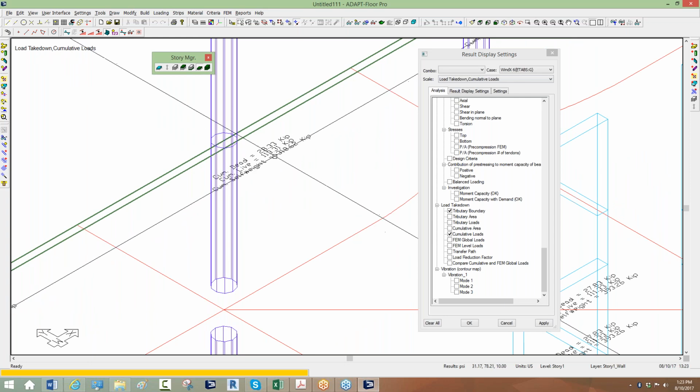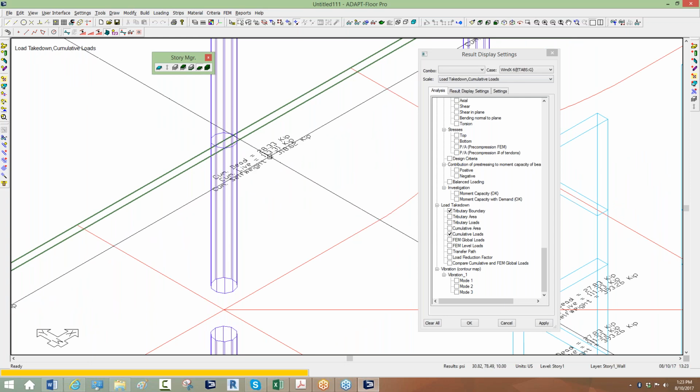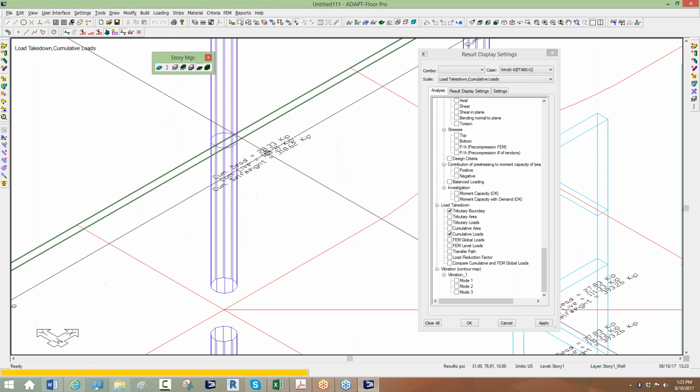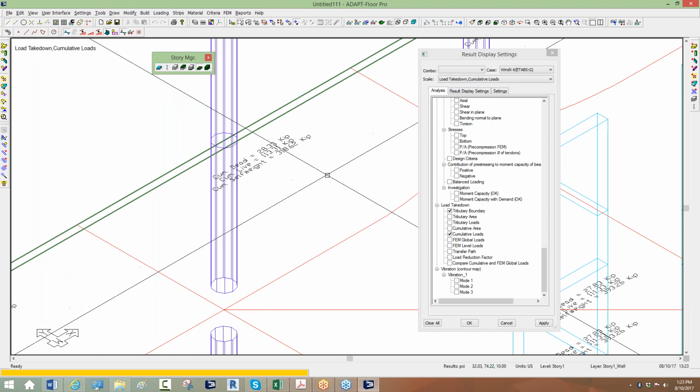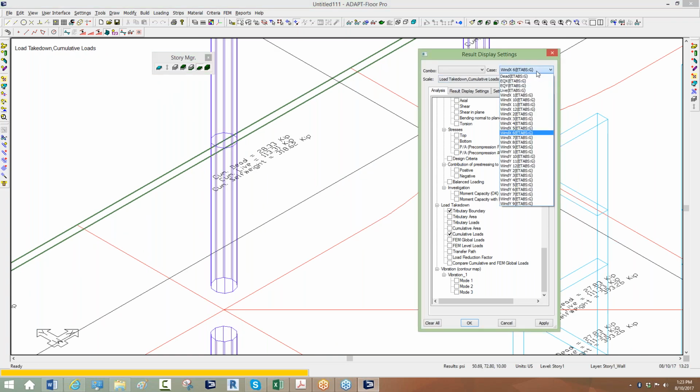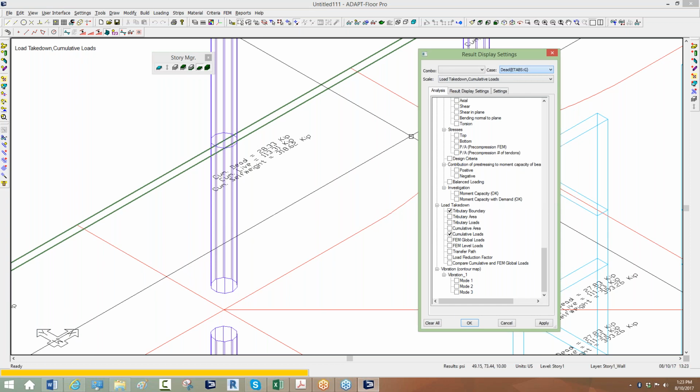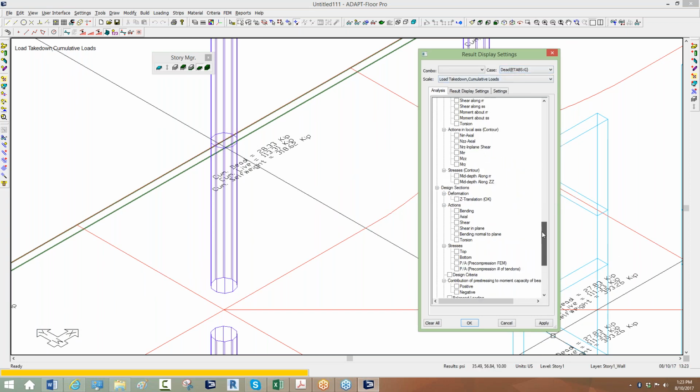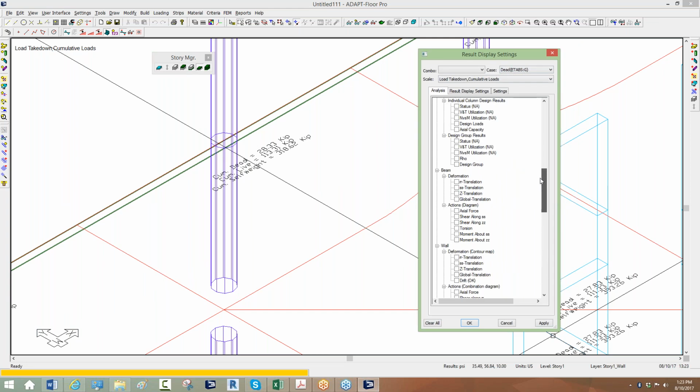If I compare that to the finite element-based solution in ETABS for dead and self-weight, if I go over here to dead load again, this is the dead load from ETABS. This includes self-weight. This is a multiplier of 1 that's specified in that program.